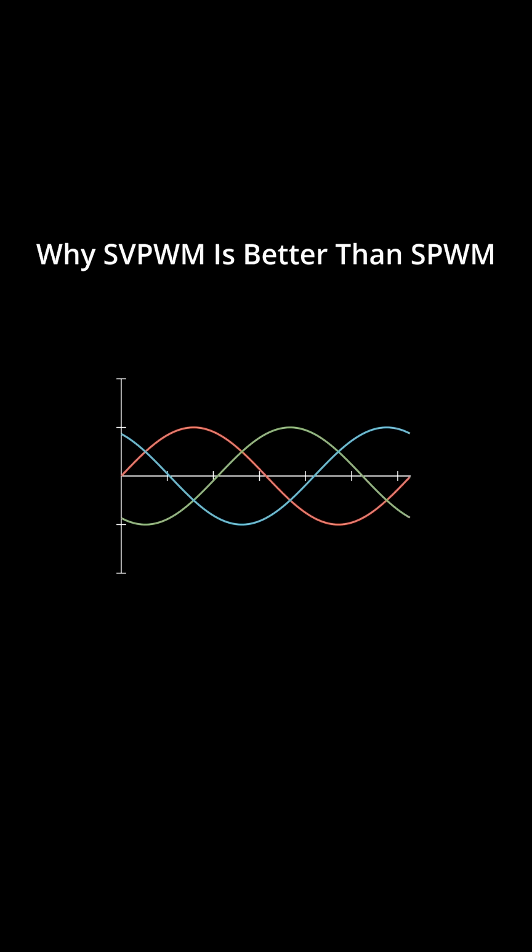However, in DC systems, we cannot directly generate negative voltages. Therefore, the sinusoidal signal we create must be shifted upward so that all its values are above 0 volt, allowing it to be modulated using PWM.